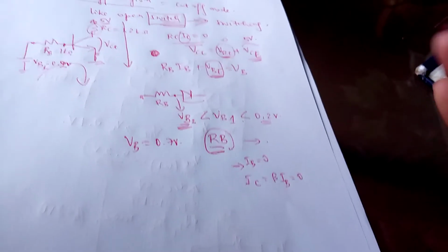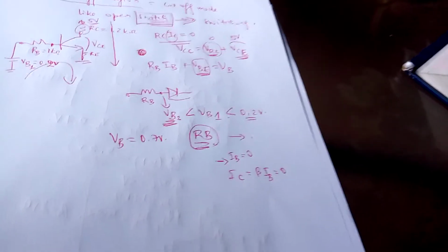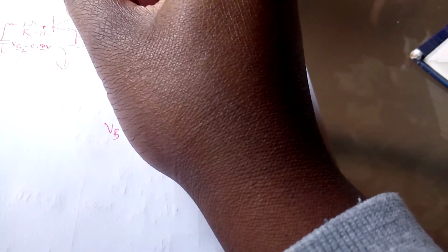In general it will be very high. Why am I saying in general? Because in the case where there's an RE, RE won't consume anything either, because if IB is 0 and IC is 0, IE will be 0. So even if there was an RE there, RE times 0 will also be 0. So VCE will be equal to VCC, which makes that voltage appear here.